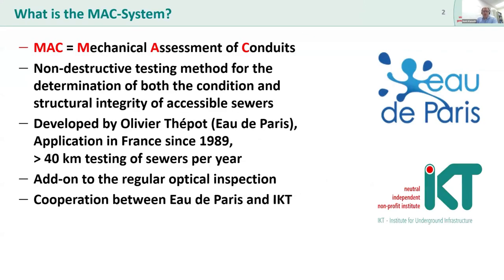Yeah, MAC is not the abbreviation for the North American fast food industry, the Big Mac or whatsoever, or the faculty where Simon Tate is working. No, it's the abbreviation for Mechanical Assessment of Conduits, and it's a non-destructive testing method for the assessment of the structural integrity of accessible sewers, which means sewers that are wide enough that you can walk inside.